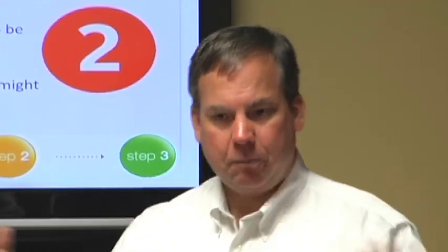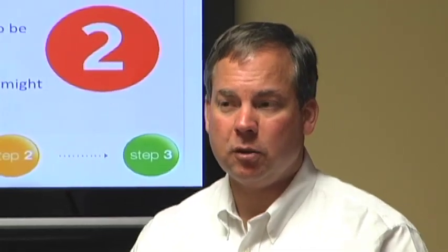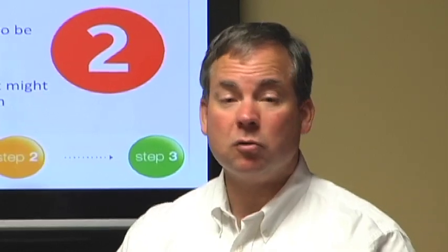Okay. If you're MatCor, we're located here near Philadelphia. The Delaware River changes seasonally. In the summer, the salt line moves up the river, and you end up with very low resistance, very salty, corrosive water. In the winter, that salt line tends to move back towards the ocean, and you'll have more fresh water, less corrosive, but also more difficult to flow current through because the resistance of the water has changed a bit.